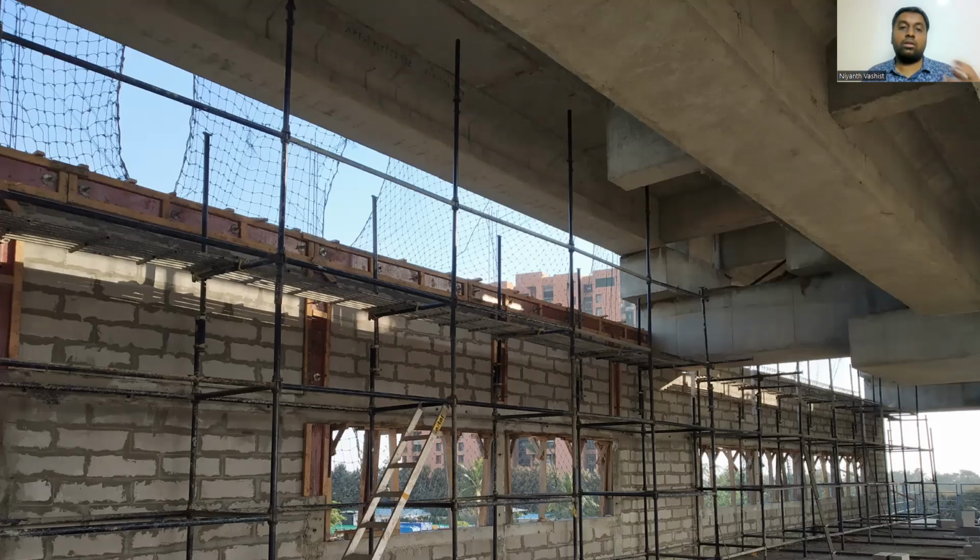Because of the wind loads and the vibration that the masonry will take in a metro station, it is very, very important to make sure we have the horizontal beams as well as the vertical mullions in the masonry work. Here you can see on top of the scaffolding, there is a horizontal beam as well. So we had to do sill beam, plinth beam, and horizontal beam on top of around 14, 15 feet to make sure you get the vertical support and the horizontal support as well.